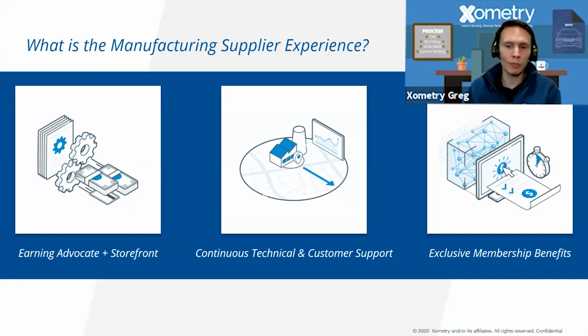Yeah, and even like we have a full QA facility out in our Gaithersburg, Maryland factory. So we actually have a lot of parts come into Gaithersburg, especially as new partners are being onboarded, because a lot of their work will go through a secondary QA at our own facility. And it is decked out. CMM, digital comparators, virtual CMM, which is actually the wildest thing I've seen. And every single type of manual gauge, profilometer, spectrometer, we have it there to help qualify and inspect. So sometimes, even if there's, for example, a specific thread, we can also do a slight adjustment and make sure that work gets back to our facility before going out to the customer to qualify that thread with a gauge.